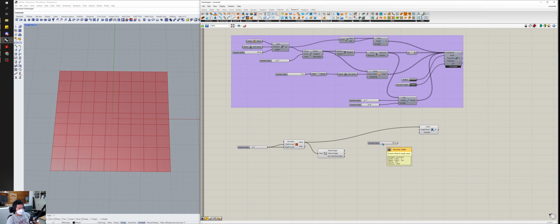So I'm going to use our slider to control these, and I'm going to set them at something pretty low for now. And then we'll see how we want to adjust them later on to create the effect that we're looking for. And as before, we still need anchor points, because we want to define certain parts of our geometry that we don't want to move when we do the simulation. So anchor points will be under goals and points.